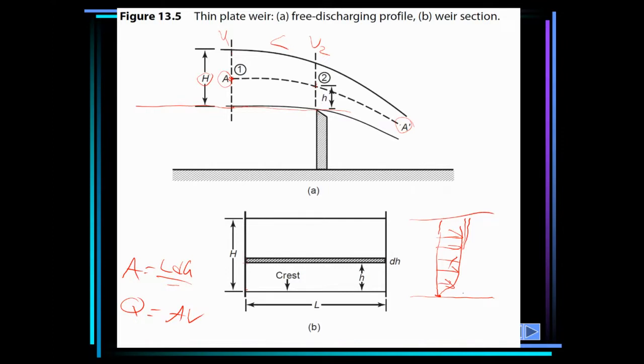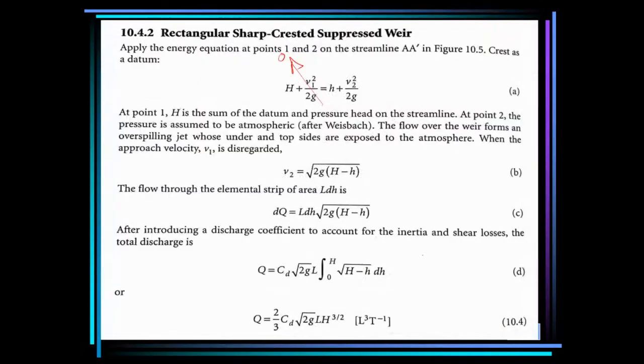So you see, when you move away from the solid boundary, the effect of shear stresses reduces. They become not pronounced to some extent. They may actually be neglected for practical purposes without introducing any error. That's why in this case we are neglecting the shear losses, because they will introduce losses which are not accounted for. To account for all these losses, we introduce the coefficient of discharge, which I explained in our previous lecture, which is simply the actual flow rate over the theoretical flow rate.